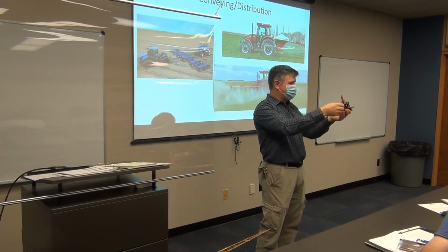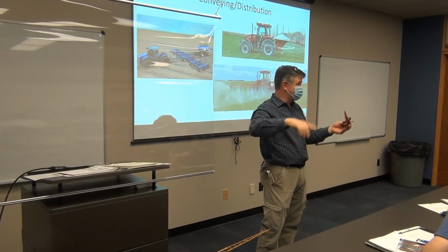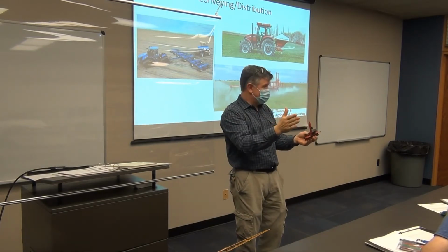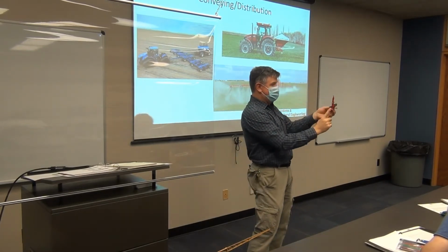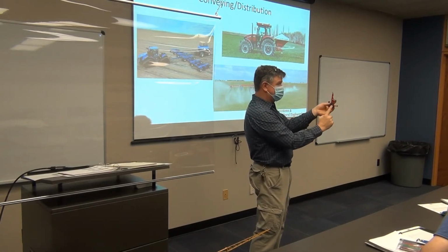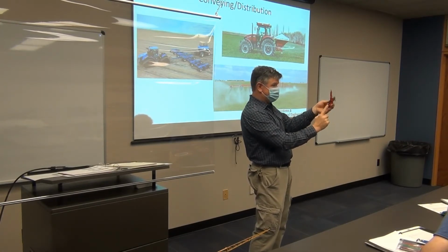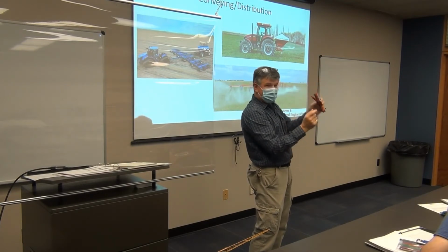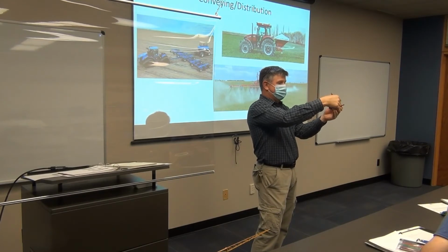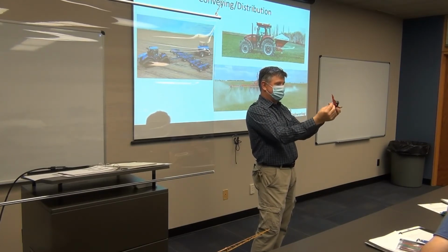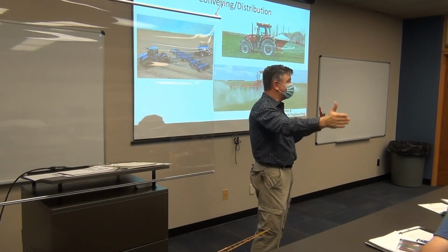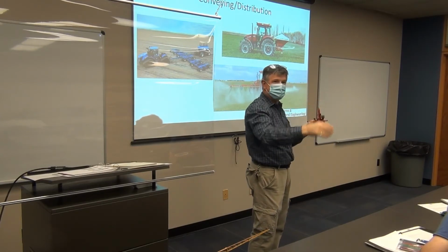So when I go across the field, this is a really wide machine. I turn around. My tractor's in the center of this thing. When I turn around and go back, how do I know where to drive? Because I really want 30-inch rows all the way along. So between the last row on this pass and the first row on the next pass, I want there to be exactly 30 inches in between. So how do I do that? This is a marker that goes out, just a disc on the end of it, and all it does is cut a groove in the soil. It just makes a groove, makes a mark.